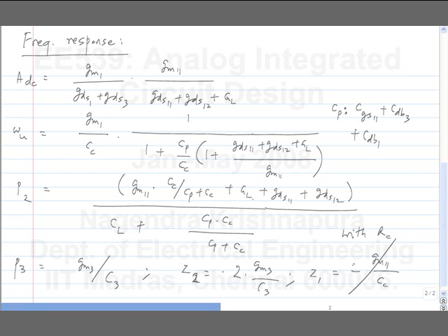Yeah, that's correct, but the CGD can be expected to be smaller than the CC that you put there. Yeah, there will be something else, but that will be small, right? The other 0 will be at a high frequency also, because the CGD is small to begin with.